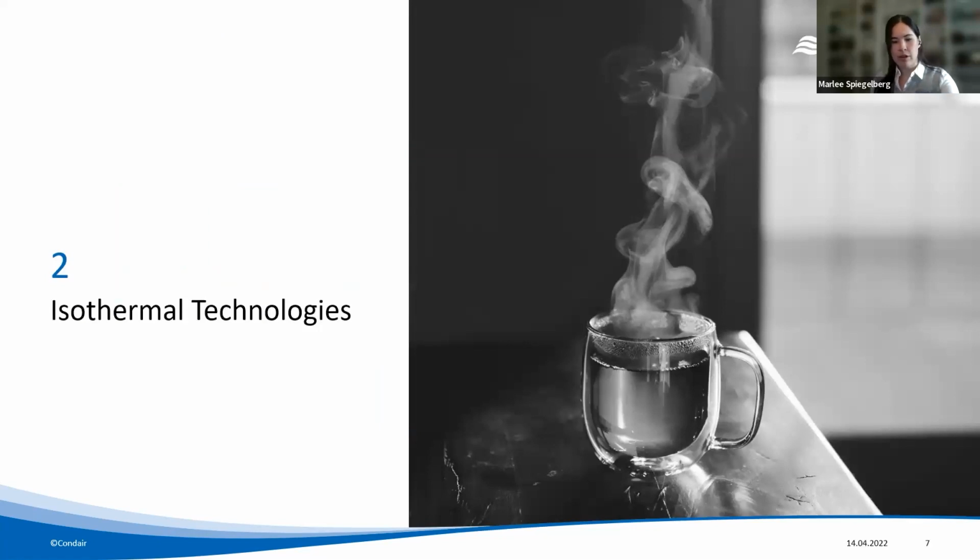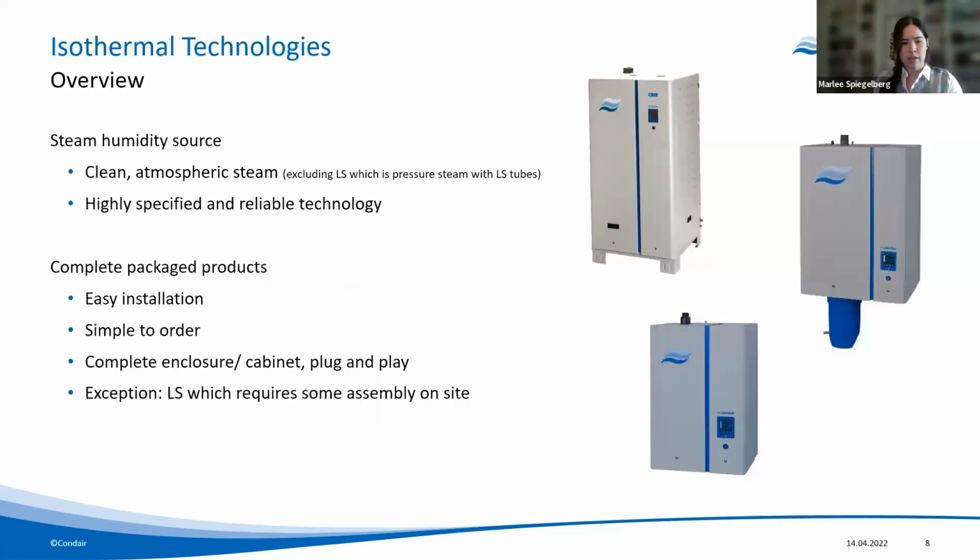Starting with our isothermal technologies, just a quick overview. Again, this is a steam humidity source. It produces clean atmospheric steam, excluding that live steam system where you're directly injecting pressurized boiler steam into the duct or air handler. We call it clean steam because you're boiling the water, so it's completely hygienic. This is a very highly specified and reliable technology. It is also a complete package product.